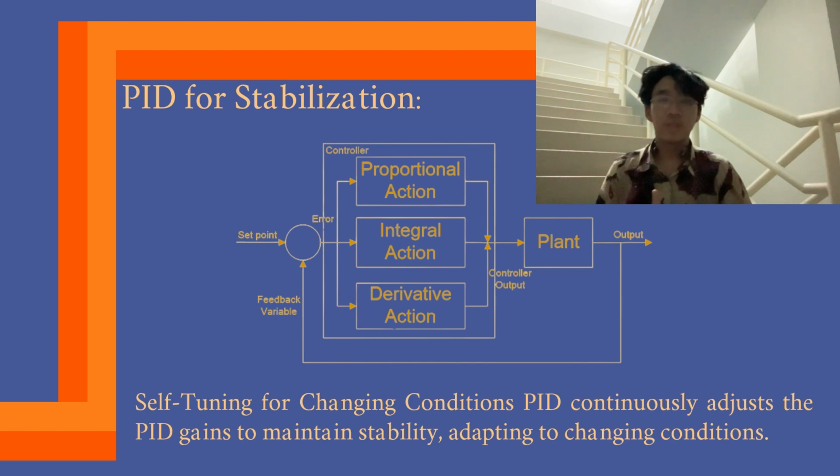And following that, we have the integral term, which considers the cumulative past of all the errors, and it calculates to make a long-term model on how to manage the errors and biases. And the final is the derivative term, and what this does is it anticipates future errors by looking at the rate of change between the previous errors, and this helps to dampen sudden abrupt changes within the quadcopter.